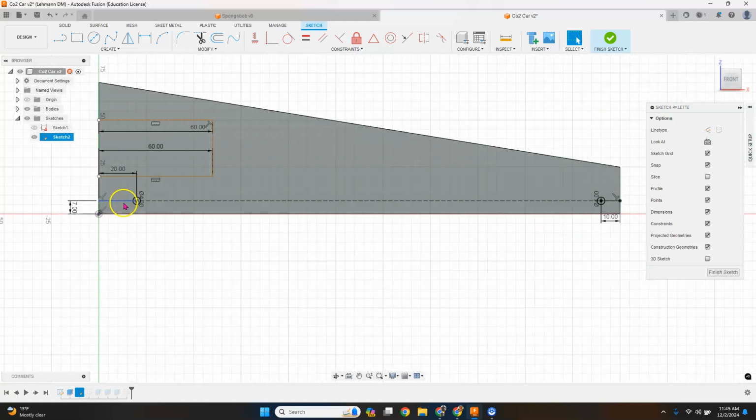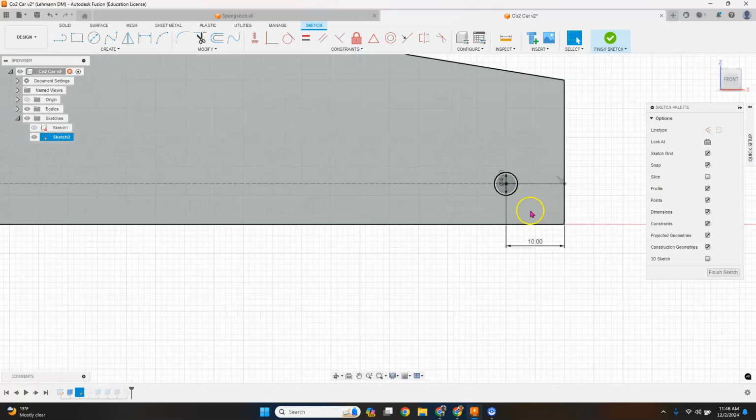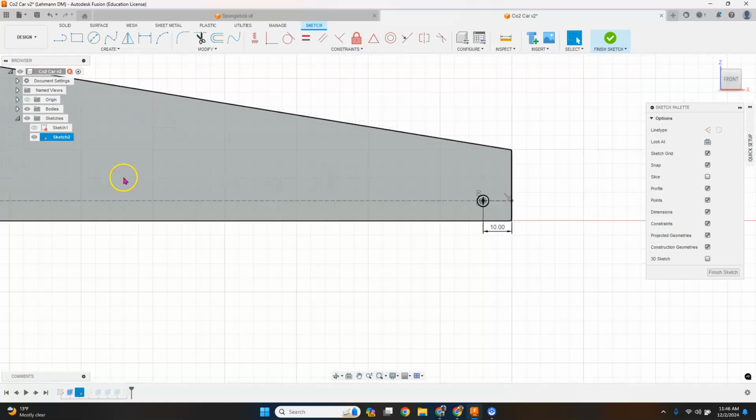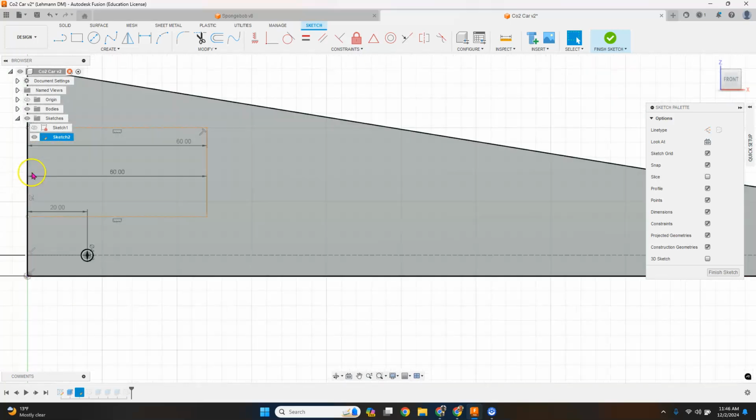Now, lastly, if you want to cut underneath, you can, but once again, you can't cut underneath this front axle hole either. So we can have a line starting here, going up and over and finishing somewhere underneath, but we cannot cut away underneath the axle holes. All right, so here we go.